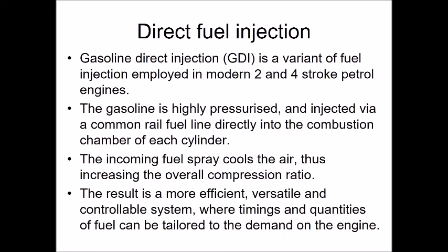We still use gasoline fuel or petrol, and what we do is we spray the fuel into the combustion chamber as the cylinder's volume is reducing, so as the piston is coming up. The gasoline is under very high pressure, and in modern engines, the pressure is getting up to incredible levels, hundreds of atmospheres, and in some cases on common rail systems they're even higher.